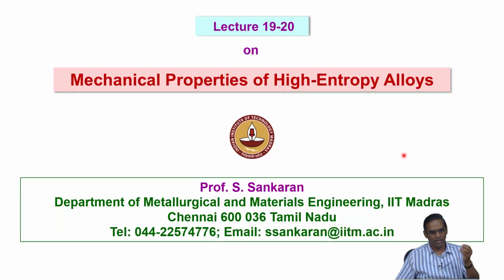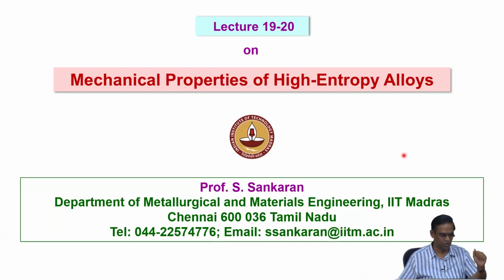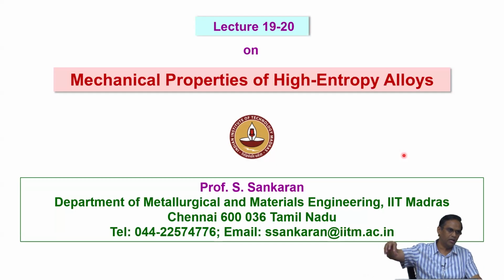So in the light of high entropy alloys, in most of them, when you add multiple principal alloying elements, the stacking fault energy comes down. Even if you go to any literature, and there is vast literature, if you look at the as-cast microstructures, you can already see the boundaries filled with quite a few dislocation arrays, and in some cases you can see a hexagonal network at the interface.